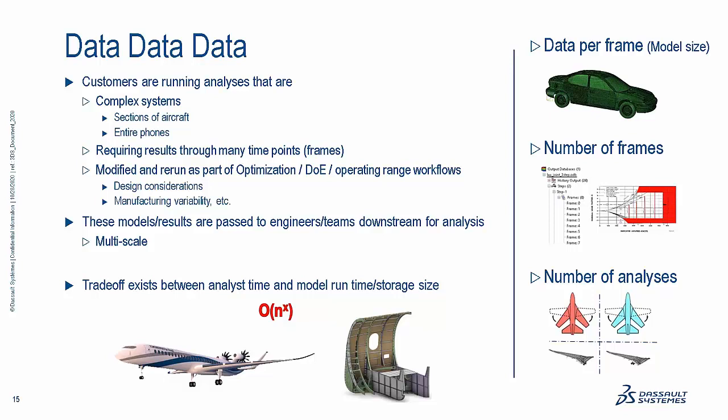Now, people with a section of an aircraft want to make sure that it works not only whenever you're doing a static loading with half capacity. You need to know that it's not going to break under a 1G turn. It's not going to break whenever it's fully loaded with fuel and passengers and cargo. And you have a number of different conditions which this needs to be run at. So you have a lot of different design considerations.